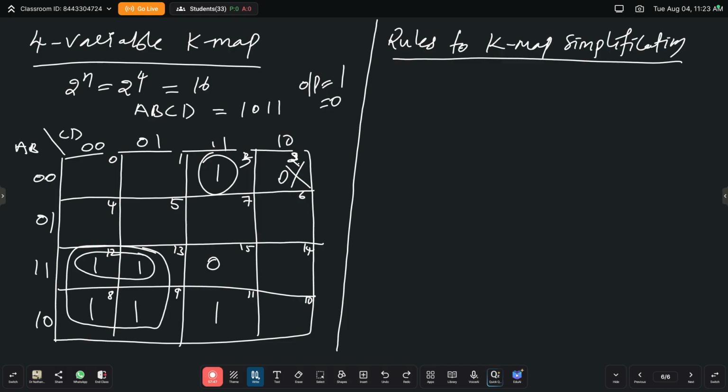Quarter group. Remember the terminology. Quarter group is the largest one, so that your designing of the circuit is very easy. Sir, can I use 2 doubles? Yes, you can design the circuit for 2 doubles also, but the circuit will be confusing. We need to simplify the circuit diagram and the Boolean algebraic expression, so consider the largest group.